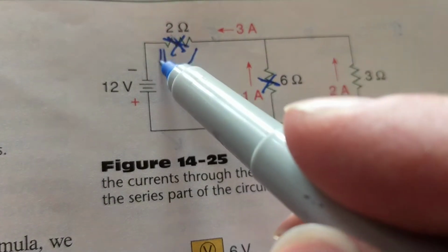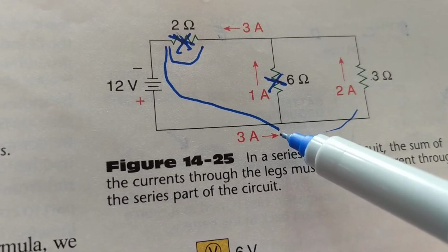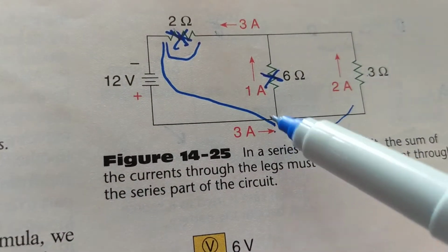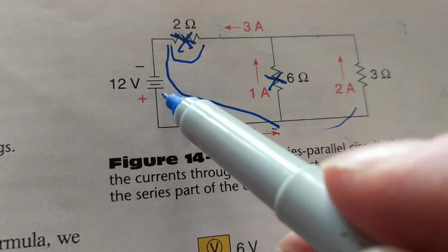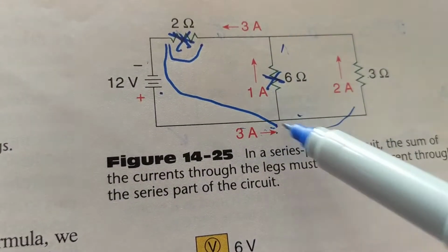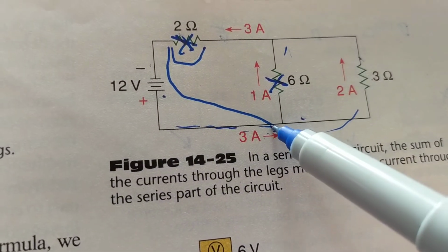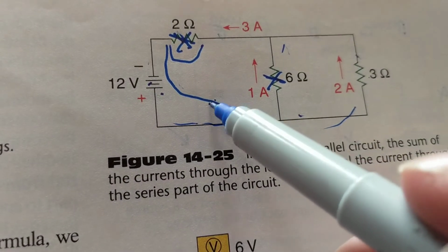Let's take a short across here and here. Uh-oh. Now what do we do? We're not just shorting a resistor. We have a dead short. We just shorted the battery, because this is connected back to positive and this is connected back to negative. Current will not flow here. Will not flow here. Guess what current will flow? Current will flow from the battery to this jumper wire and back to the negative, because this has the path of least resistance.